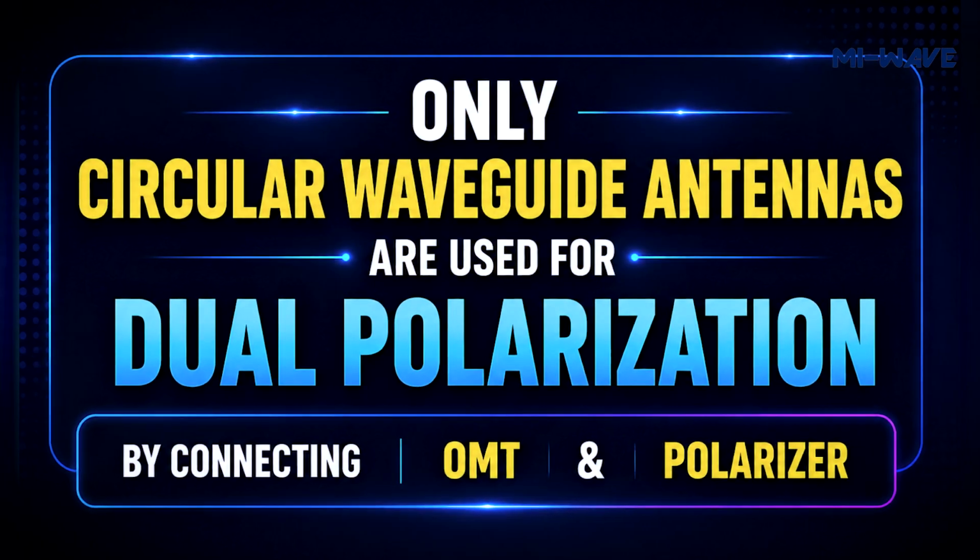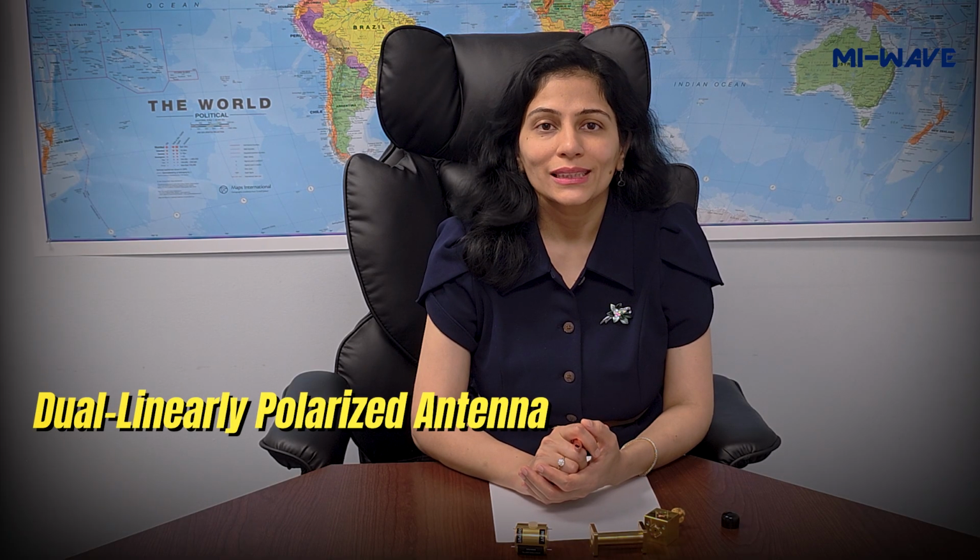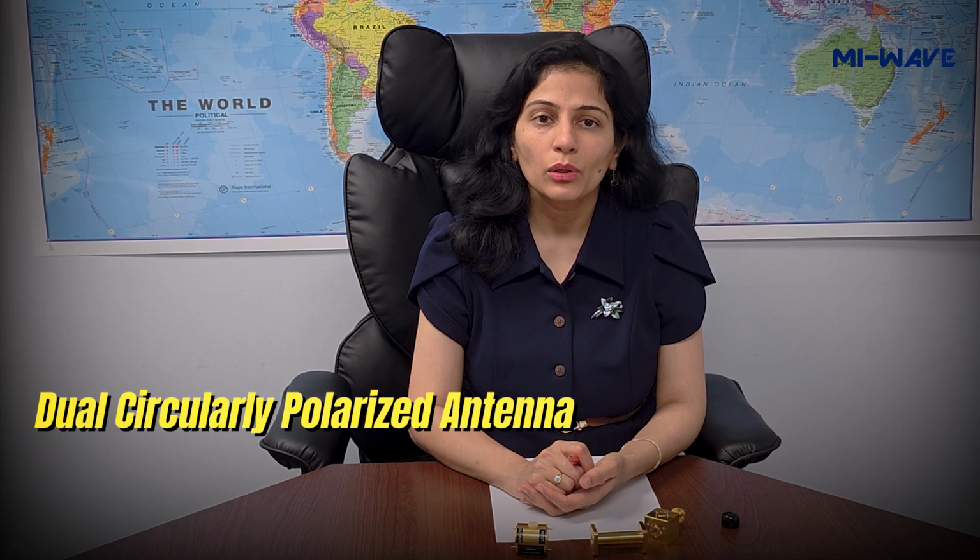Here is one interesting part. Do you know that only circular waveguide antennas are used for dual polarization by connecting an OMT and polarizer? When a circular waveguide feed antenna is connected directly to an OMT, it becomes a dual linear polarized antenna, supporting both vertical and horizontal polarizations simultaneously. If the same circular waveguide feed antenna is connected to an OMT through a circular polarizer, it becomes a dual circularly polarized antenna, supporting both RHCP and LHCP simultaneously.